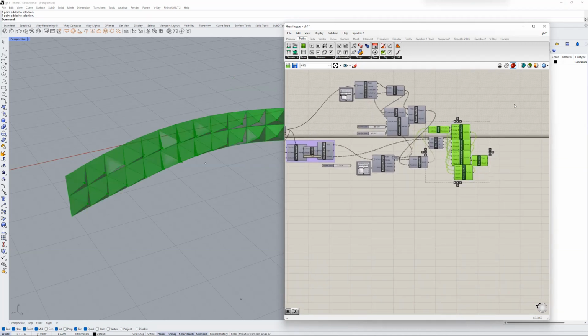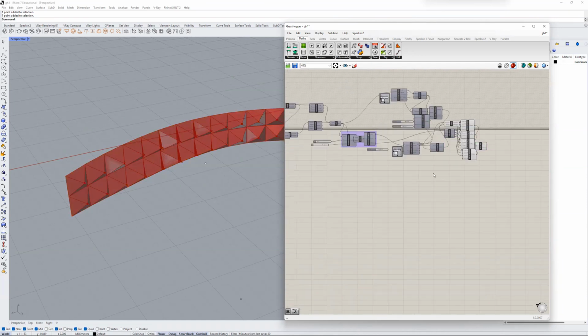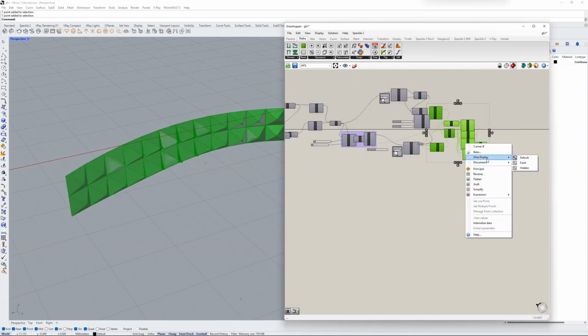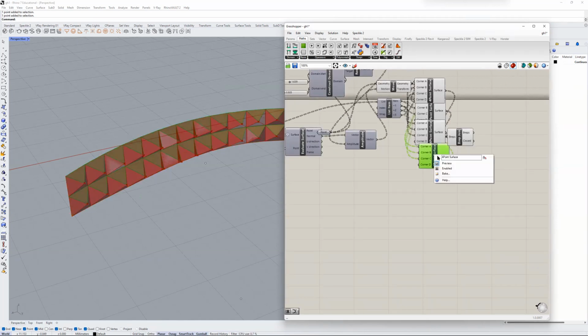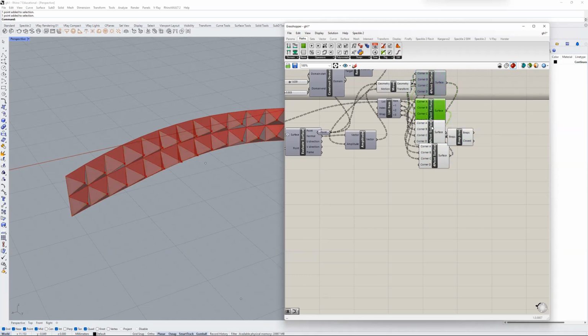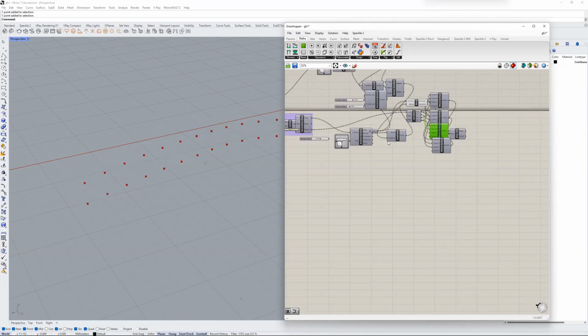You can also do this by, if I wanted to hide this again, right clicking on something. So I guess I can't do it in a group. No, I can. Okay. So right clicking and then turning the preview off. This right click method only works on individual blocks, so you can turn off preview for individual blocks.